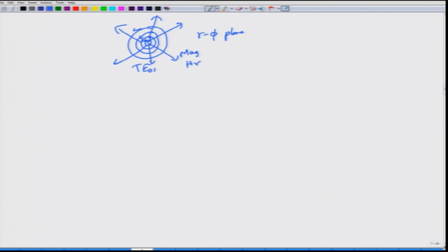For the transverse magnetic fields, E phi is equal to 0, Er would be something like J0 prime kappa r of course, and then you have Hz equal to 0 and Hr equal to 0, but because Er is present there will be H phi. So, the field lines actually just change. What you would have called the field line for E in the TE case becomes the field line for the magnetic field in the TM case.